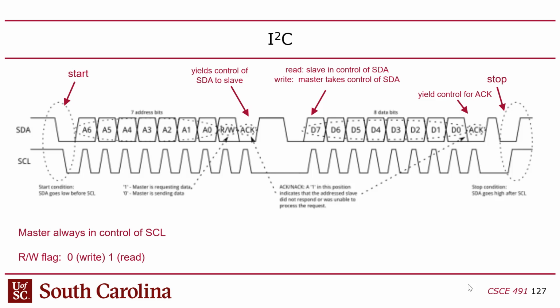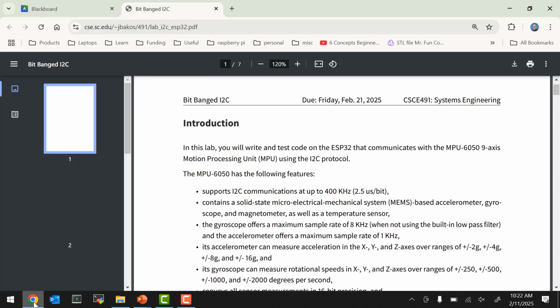However, you would think that you just mark it as bidirectional, right? No. Arduino still requires you to change the mode of the pin as you switch from reading to writing, even though it's open drain, which is really dumb. The whole point of open drain is that you shouldn't have to do that, but you do. So there are two modes, and they're both described in the lab sheet.